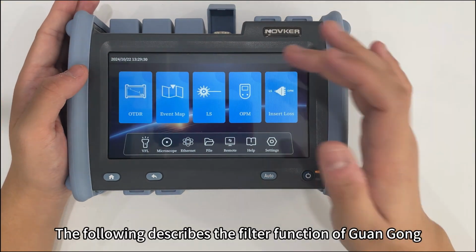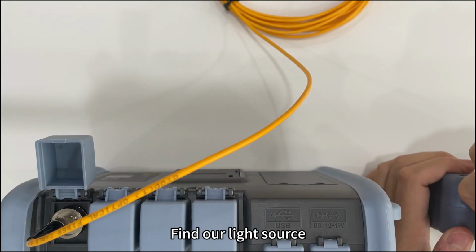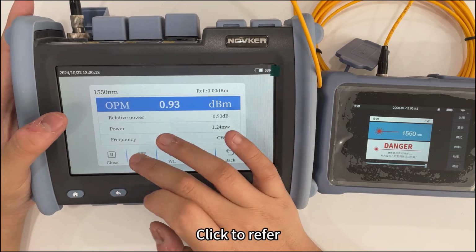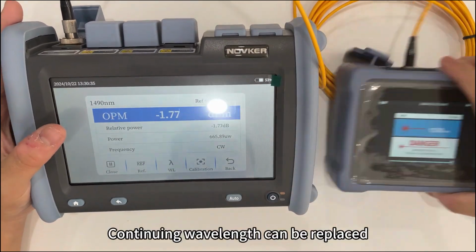The following describes the optical filter function. Click on the optical filter. Plug the fiber into the optical filter interface. Find our light source and switch to the corresponding wavelength, 1550. At this point, you can see the change in the current power value. Click reference value. The current power value can be set as the reference value. Click to switch the wavelengths. Wavelengths can be replaced.